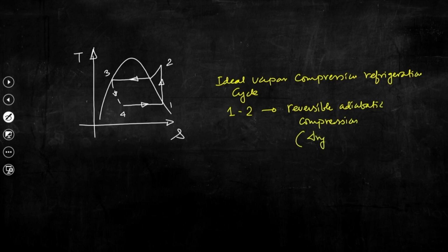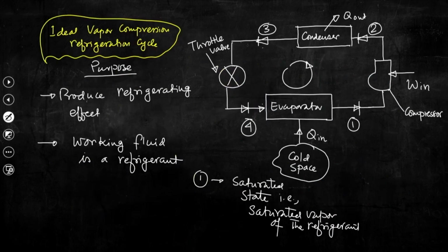So, this is dry compression. Why is it dry? Because try to understand, the refrigerant or working fluid available at the inlet of this compressor is saturated. It is not a two phase mixture.